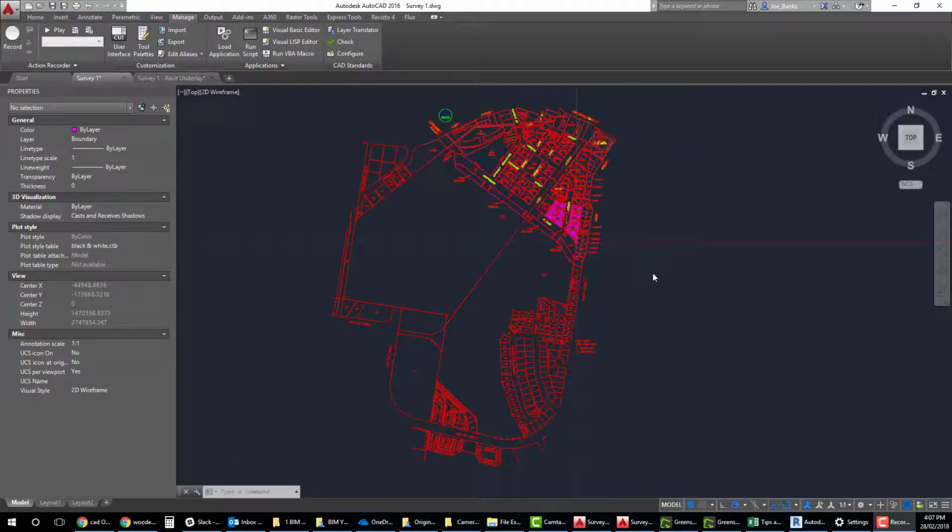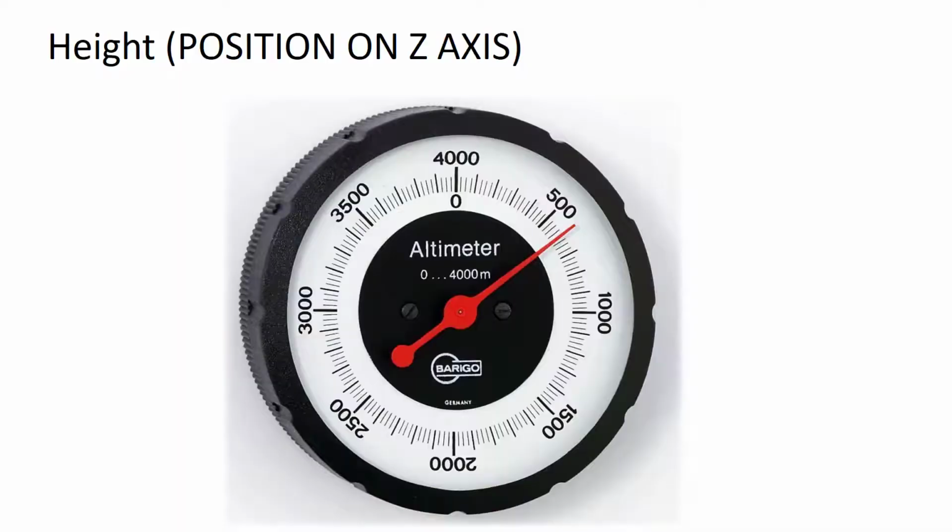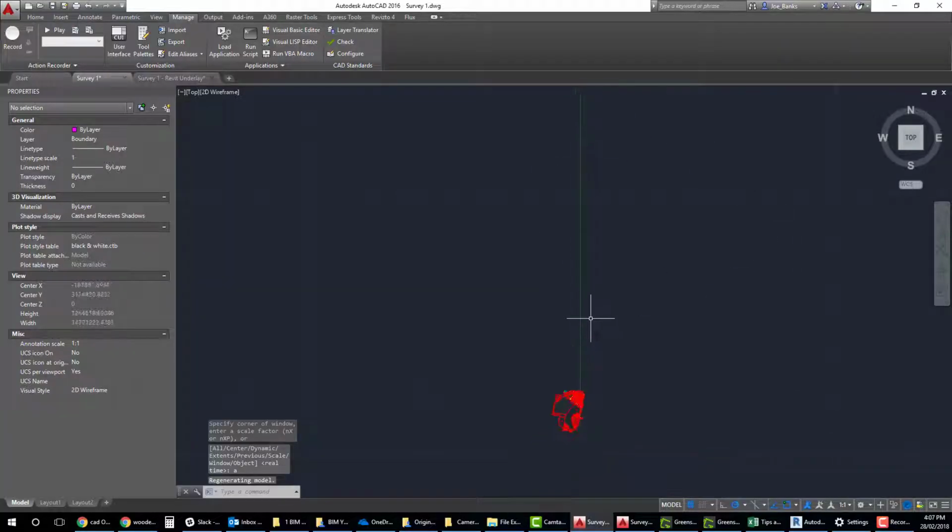Now, one of the other important things to check is to make sure this isn't outside the maximum allowable radius within Revit, both in the X and Y and in the Z direction. So I'm going to do a zoom all just to see what's happening. It looks like there seems to be something out here that's causing that to not just fit nicely around our geometry.